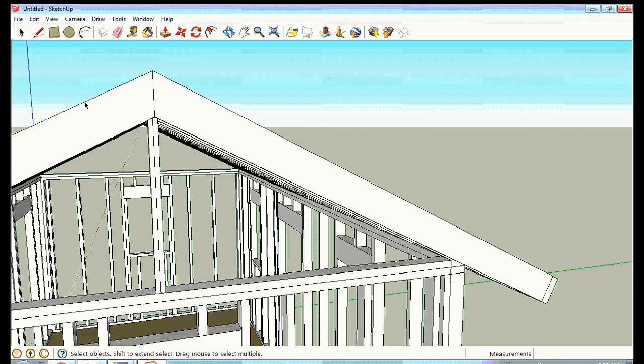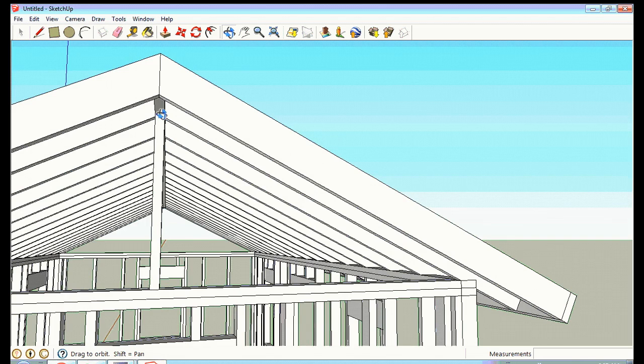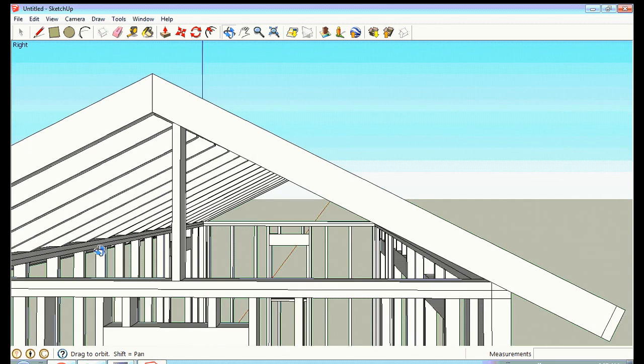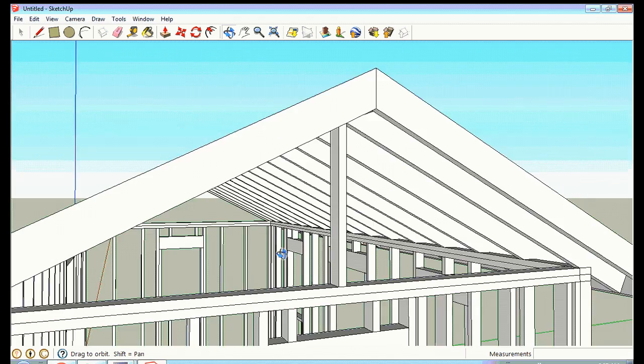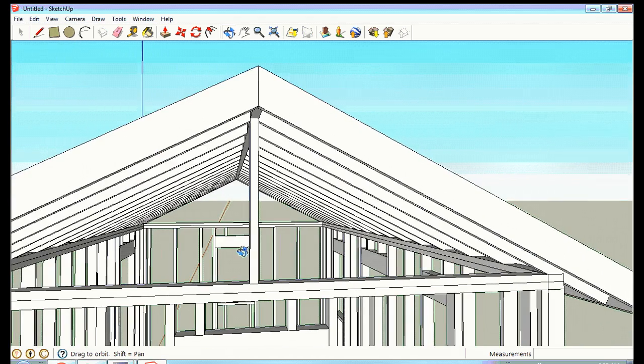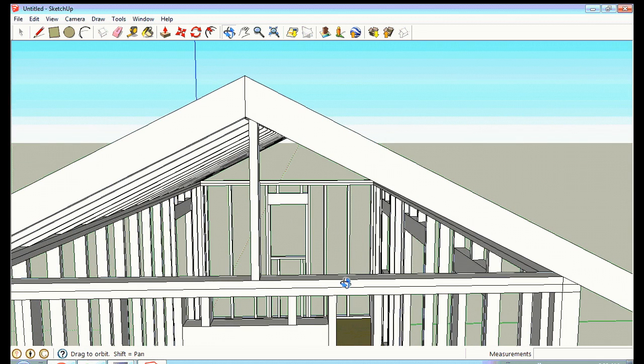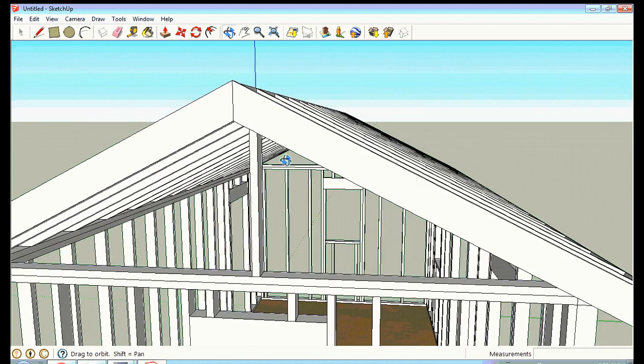Now you know it pulled in the second line, but now that will line up. You can see it lines up directly underneath the roof beam, and that is my center support. That is the main structural support for this end wall here. You may want to double this if you wanted to. You may want to put in an extra support in the center if you're going to have a lot of snow load, but generally, because you're going to have more supports on this side and this side, that would be enough center support for that roof peak.